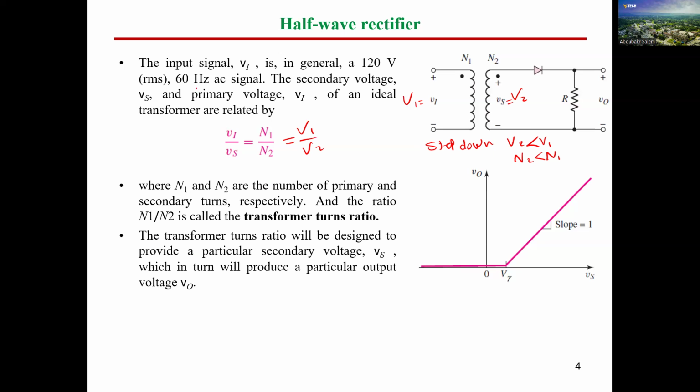So in this case, you expect the volt in the first house close to the transformer to be relatively high. So the domestic load 120, 110, 115, it could be any of these, depending on how far your house is from the transformer. If the transformer is relatively far from your house, the volt would be less. If the transformer is very close to your house, the volt would be high. But by the end, we call it single phase domestic load or domestic supply.